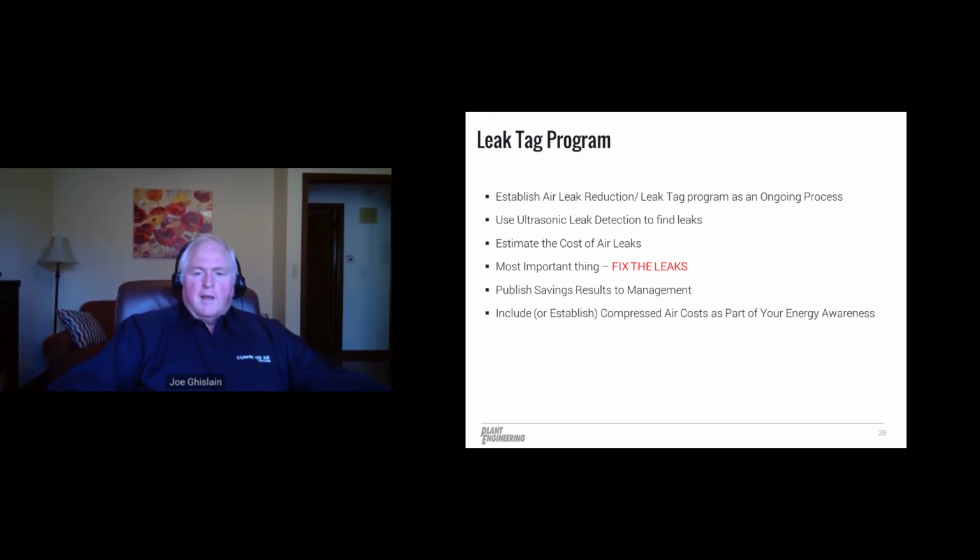I emphasize that, and everybody goes, "Hey, thanks, Captain Obvious. That's the whole purpose." Well, I went to a lot of plants when I was the global energy manager at Ford that did a great job of putting it in the PM system, logging it in, saying how much it was, putting leak tags out, and having PM orders, and they just never fixed them because they couldn't get the maintenance people. They couldn't get the release for the maintenance people to do it.